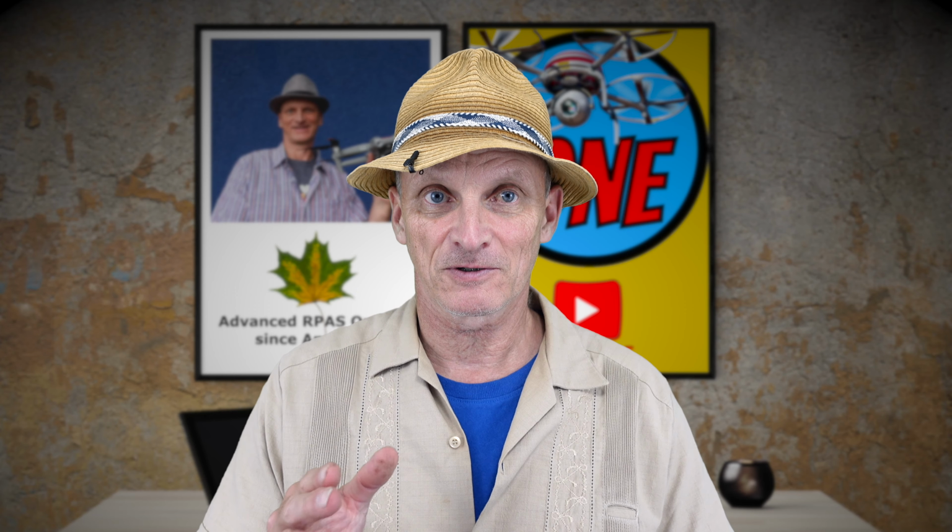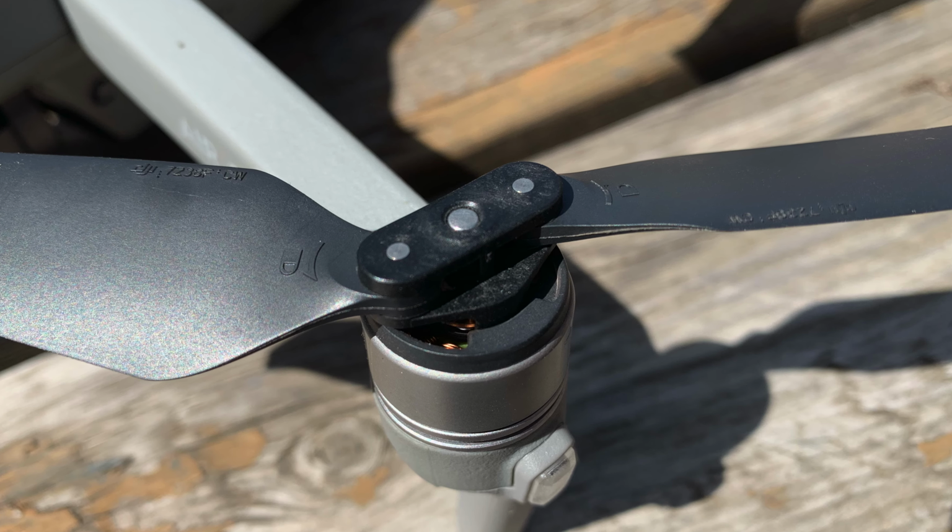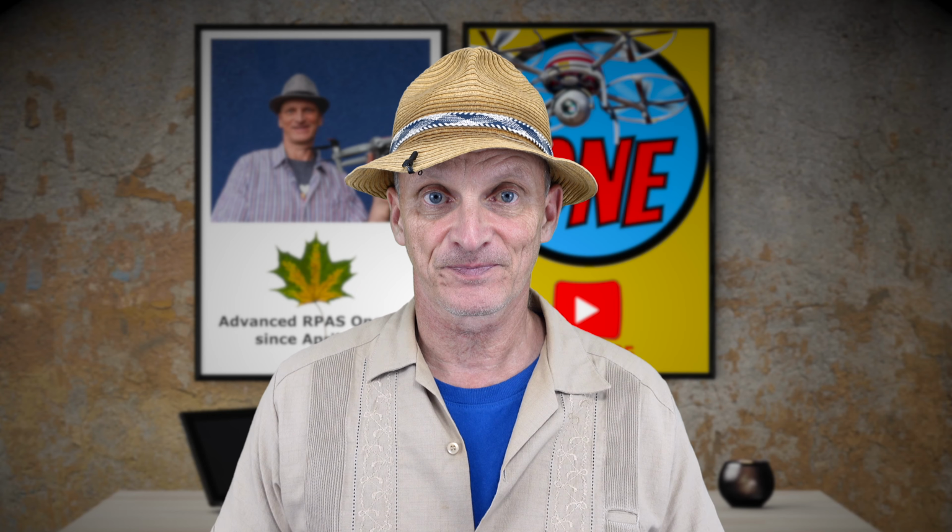Inspect them before and after every flight. If you see any chips, cracks, or deformations, replace them. Also check the mounting mechanism. A loose propeller can cause a crash.